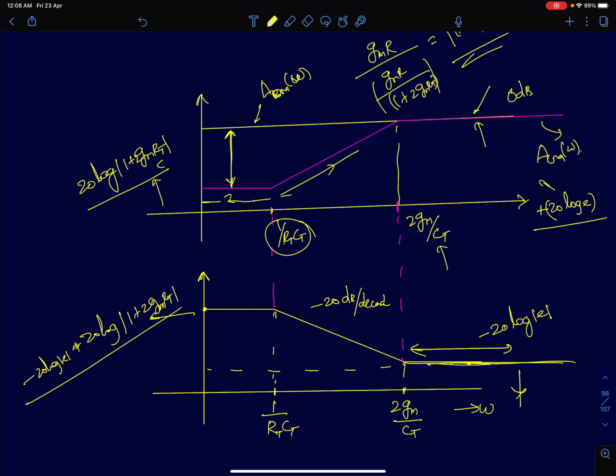But what we are seeing here is that CMRR was very high at low frequencies, but at very high frequencies, CMRR becomes very low. This is the point where the common mode gain becomes equal to the differential mode gain. That's why your CMRR is decreasing, because even though differential mode gain is remaining the same, common mode gain is increasing.